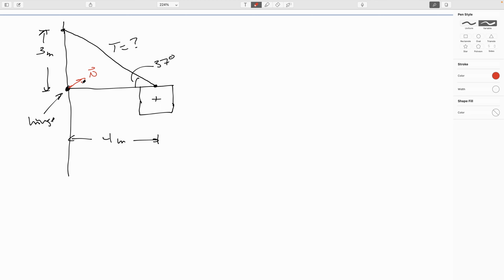You would just in general put the normal force off in some direction, and we don't know what this angle is. And we would be dimensioning out an x and a y component for the normal force. And before you think that seems a little crazy, if you look at the construction of a hinge, what you've got is a pin that's sitting inside a sleeve. And so when the hinge is hinging, the pin is free to sit wherever it needs to on the inside of the sleeve. And so it can exert a normal force, say, in that direction if the pin's like that. If we're down here, it would be exerting a normal force down, and so forth. So there's always a little bit of slop, and the point of contact between the pin and the sleeve dictates where the normal force is pointing.